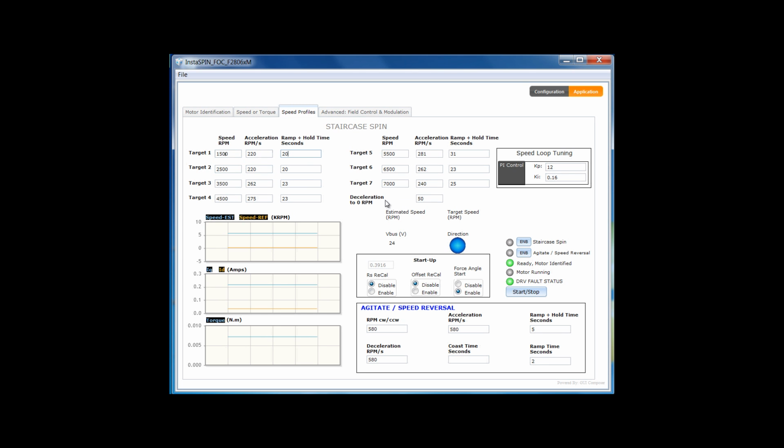And you'll notice at the end, this is, like I said, set up typically to do a full spin cycle up to very high speeds. At the end, we typically want to decelerate back to stop. The spin cycle is over. You want to make sure that you do this slowly. When you're going in these high speeds, and especially if you're using some field weakening, you're going to have a lot of voltage that can be dropped back onto the bus. And if you decelerate too quickly, that can go back onto your bus. And that's a system type of topic that you need to address in a real product when you actually make your final product anyways.